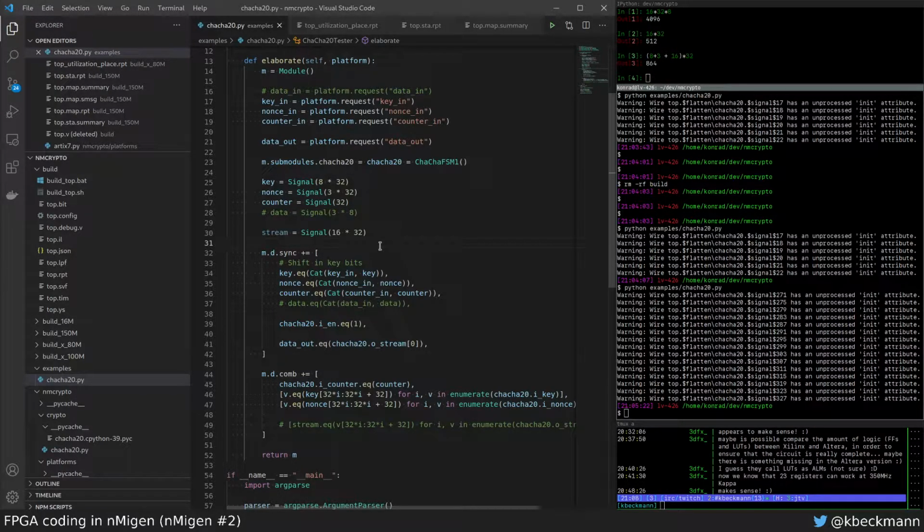Maybe RAM is the way to go, and muxes, so that you store the bits into RAM and then you load the registers from the RAM. That way you don't get these sort of big registers, like this huge register array.